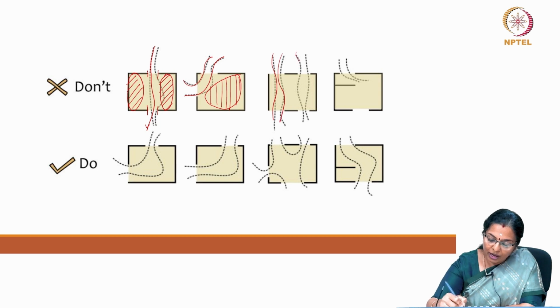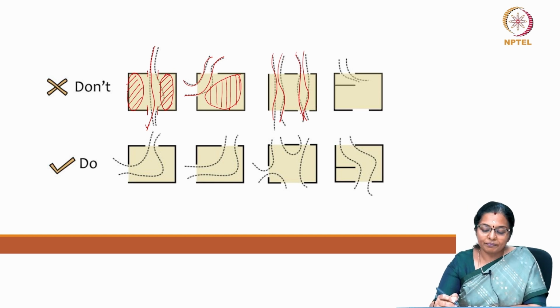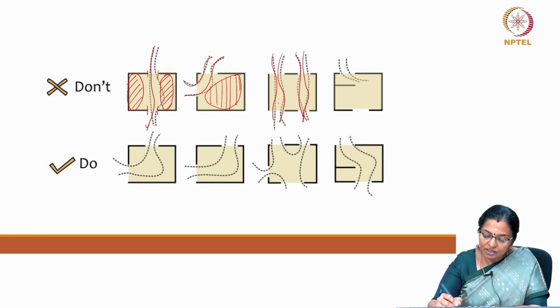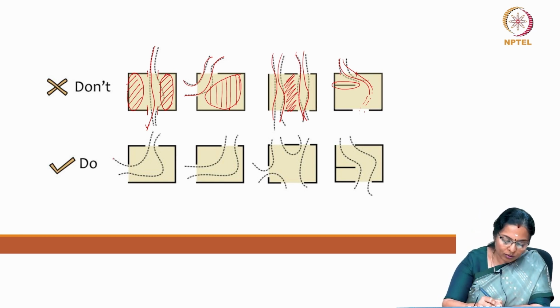Having too many openings is also not a great idea. It's not a bad idea, but what happens is you still have areas where you will not be able to perceive breeze movement, and try to avoid having openings in areas where there is an internal obstacle, because the wind velocity fizzles out by the time it comes onto this side. What is it you must do, or what is the best case scenario? The best case scenario is to have